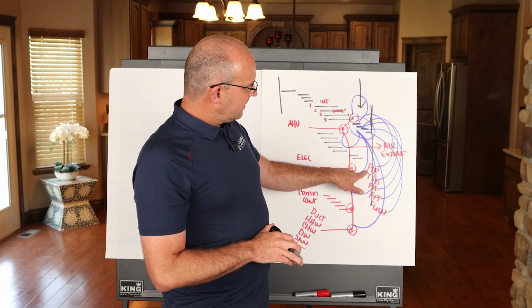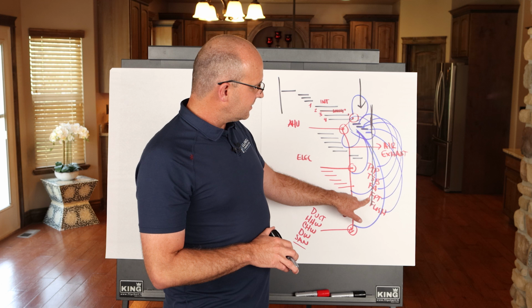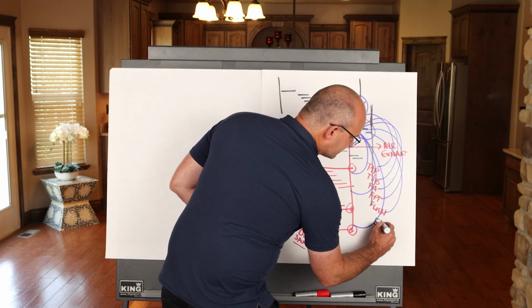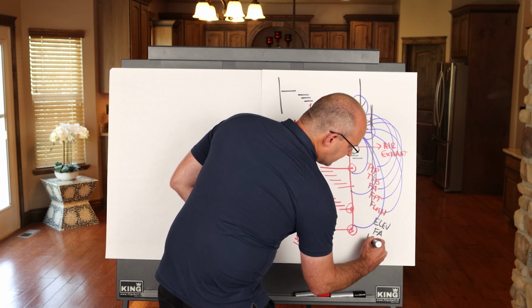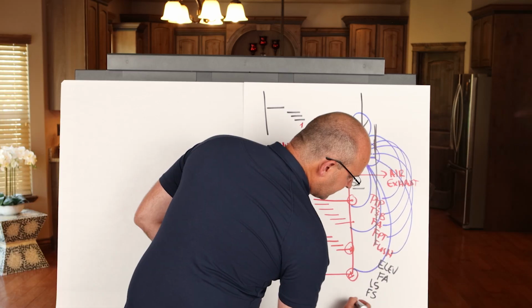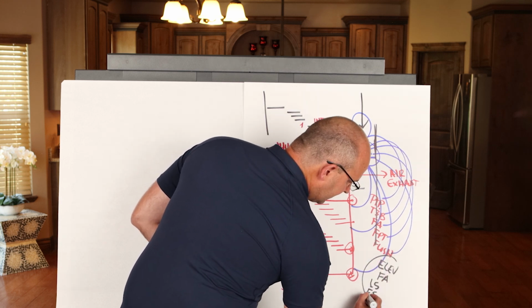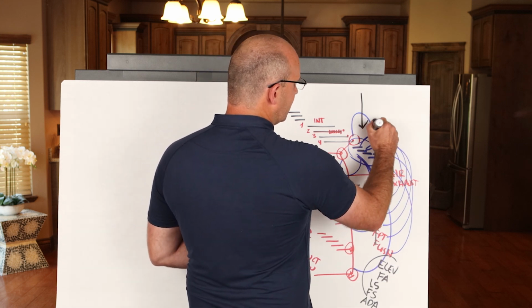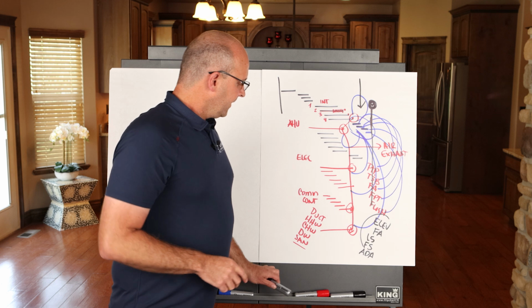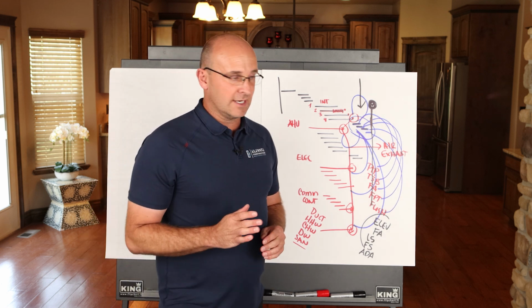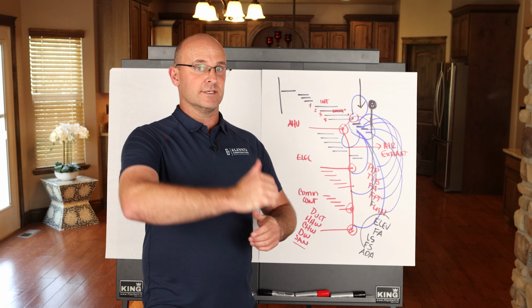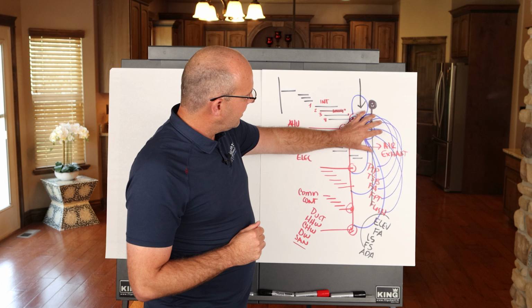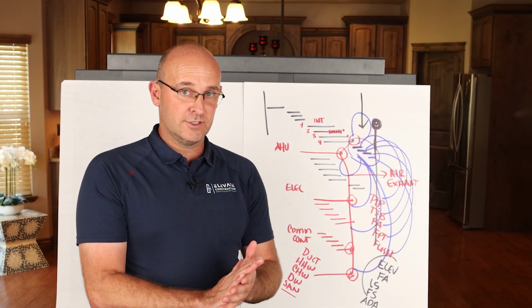So even with the point-to-point test and balance, fire alarm integration, functional performance testing, and flush, you'll also want to put in here your elevator inspections, fire alarm testing, life safety inspections, fire sprinkler, anything over here, ADA inspection. This all has to go with it in order for you to meet this end milestone of substantial completion. Now, you're probably like, Jay Money, this is a lot. Here's what I want you to take away from this. I want you to know how to visualize it. We already drew that. I want you to know how to approach the individual systems and how they tie to the overall commissioning. You can do this now.